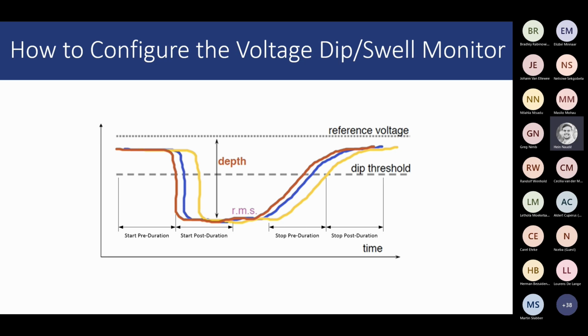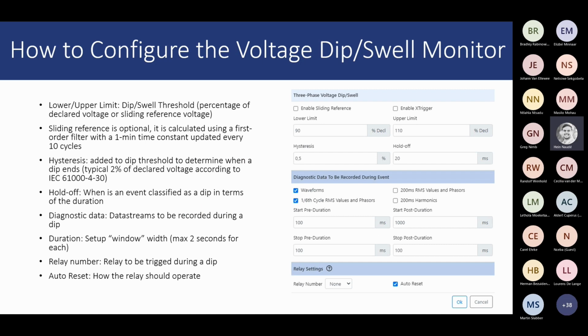And just getting to your question on seeing the current when a circuit breaker operates, you can actually use your circuit breaker status, connect that to a digital input on the VECTO 3 to trigger a recording when that circuit breaker operates or changes state. It will also then capture all of this information, the voltage and current waveforms and RMS, when that state changes. And again, you can select the period that you want to record that data. So that's definitely possible.